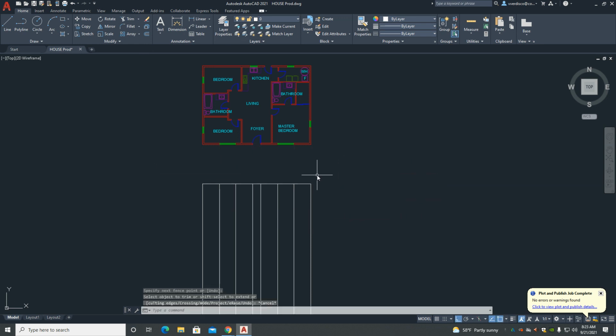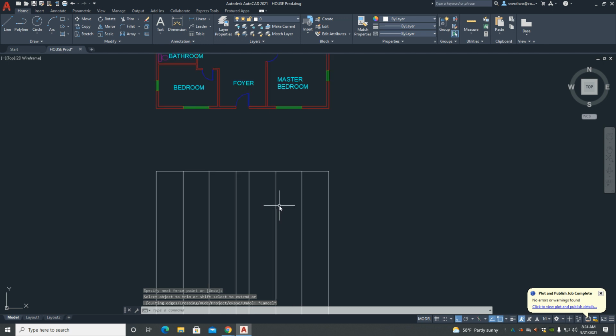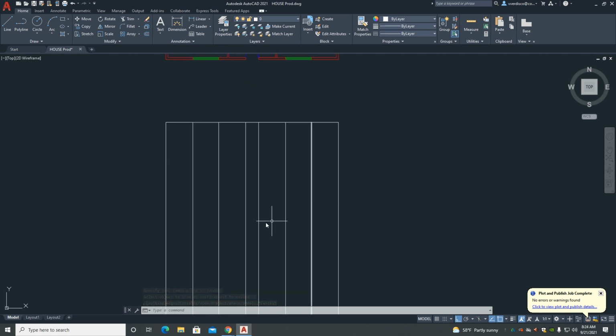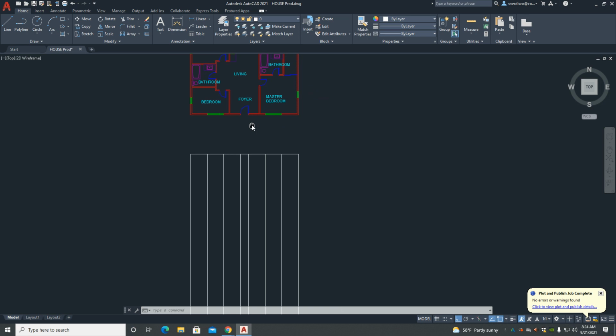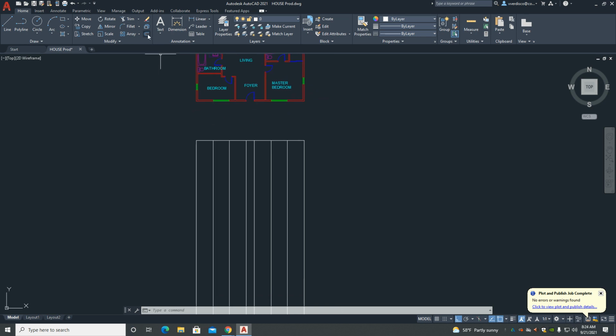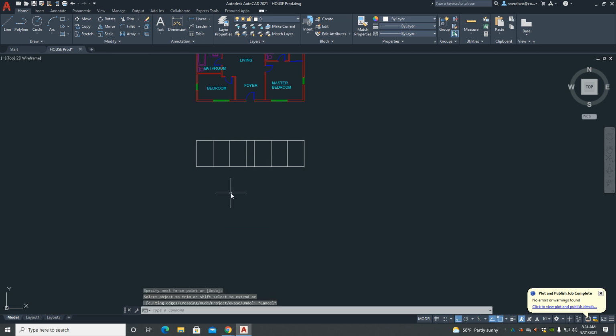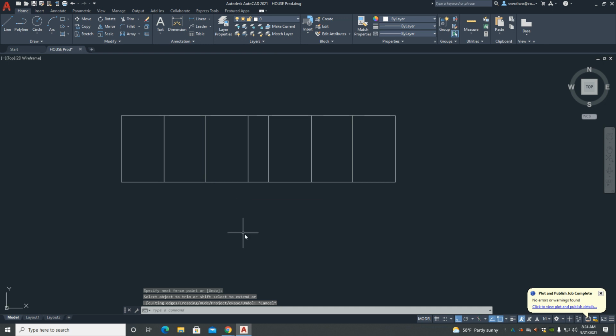All right, so now I want to put a line down here so that I have the base of the house. Typically it would be somewhere around 8 foot 3 inches, but I'm rounding off for the video here. So to simplify things, I'm going to offset an even 10 feet, just like this, and get rid of that by trimming. Now we start filling some stuff in.